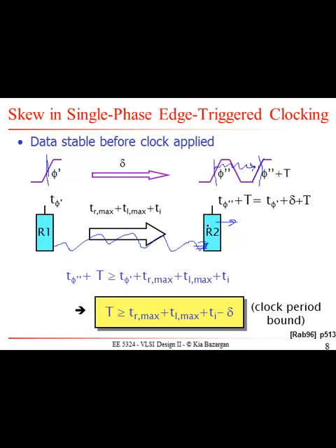timing constraint is honored. And essentially, if you write the equations for that, you would know that the time from the time that you release the data, so the time that your data gets released here, that's t phi prime, and you're going to go through the logic max and register max, and TI being the wire delays, whatever wire is connecting your combinational logic to R2.